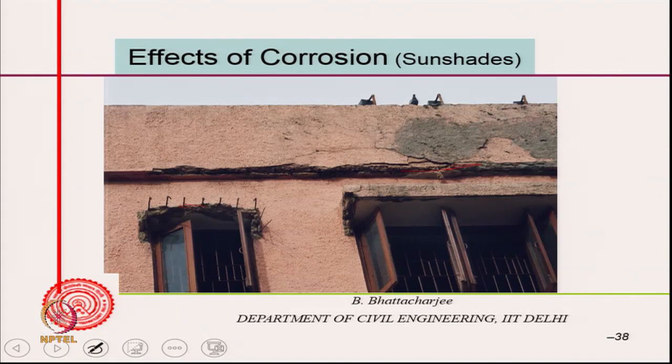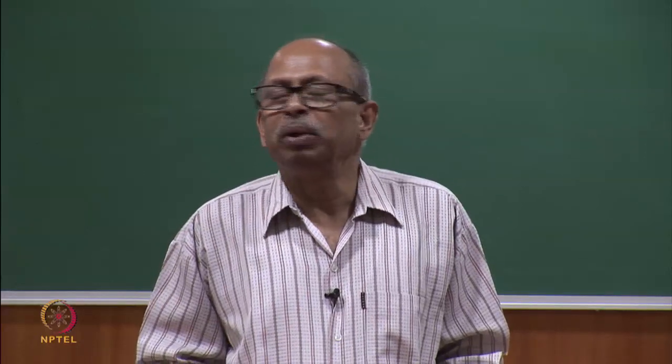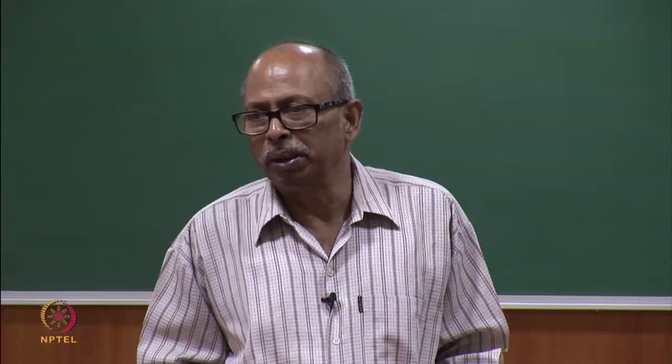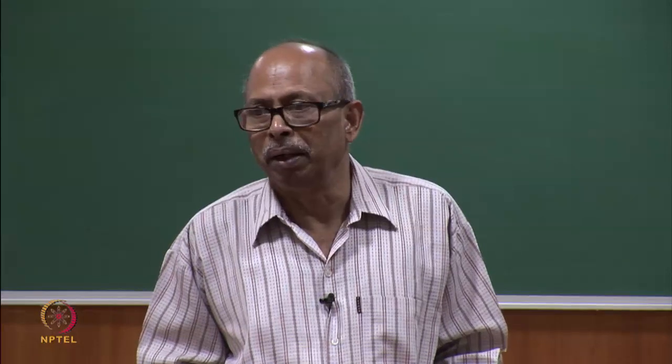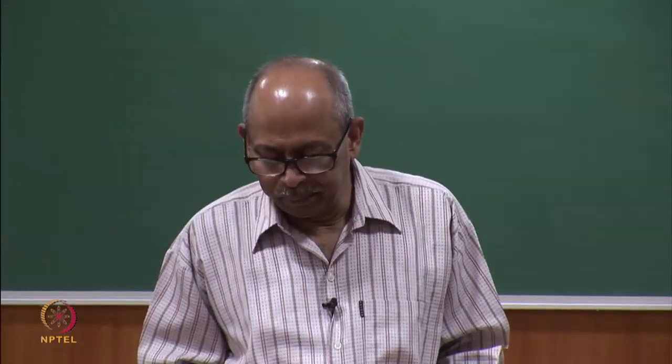If you see rust staining, if you see cracks with rust staining, then you might open the crack and find that an expansion has occurred, and it must be parallel to the rebar, right. So, corrosion can be identified very easily.